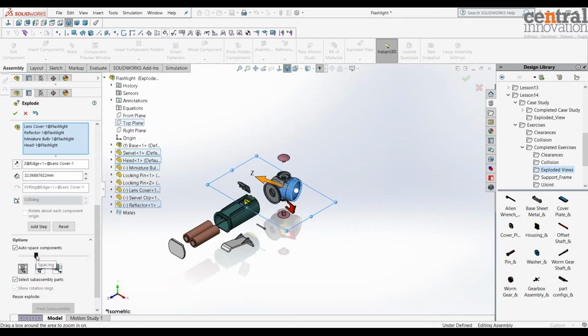And then there's a bounding box, which SolidWorks will consider for the selected components. So you can select between the center, use the center of the bounding box, use the rear of the bounding box, or use the front of the bounding box. I will stick to the center of the bounding box, and then I will move them using this axis.